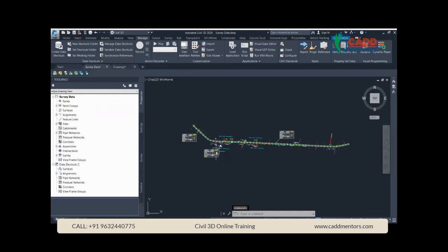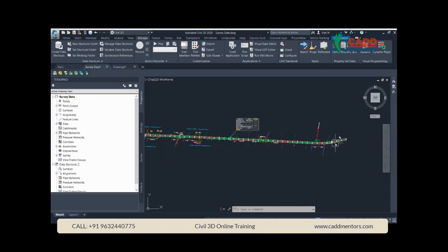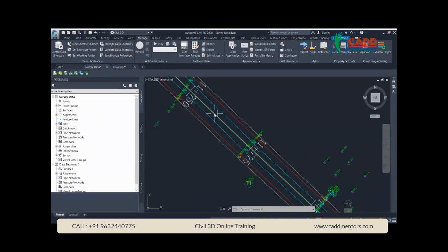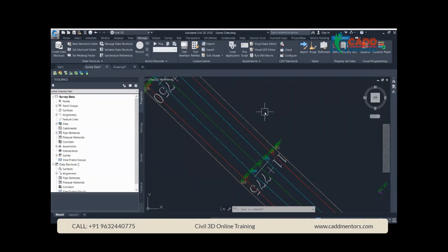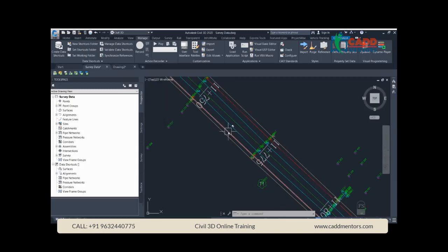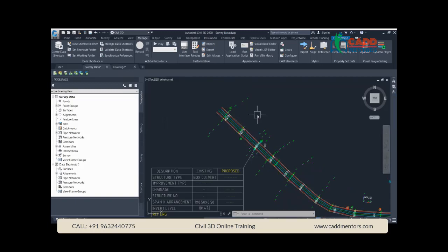So this is how a topo survey is collected on existing roads today. What they do is take the existing center line and the existing carriageway edges, and the shoulder if there is one. I'm assuming that you are all familiar with the cross sectional elements of the road. When I say cross section elements, those are carriageways, shoulders, and the embankments. Depending on the project importance, they collect the data at every 50-meter interval across the road.